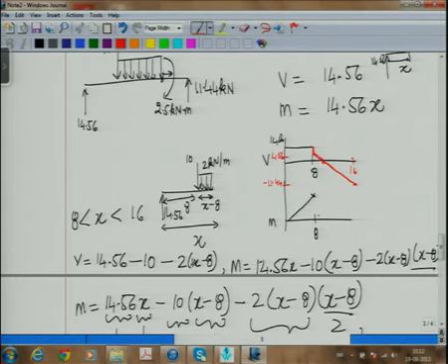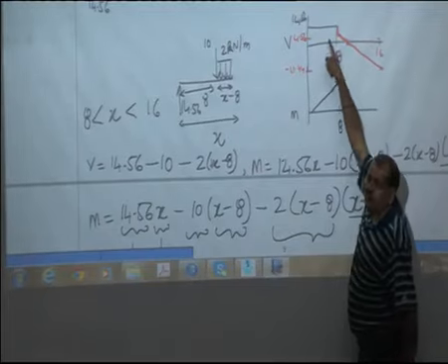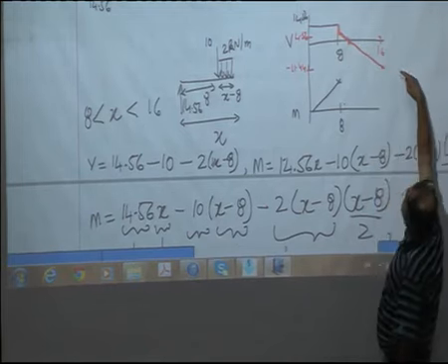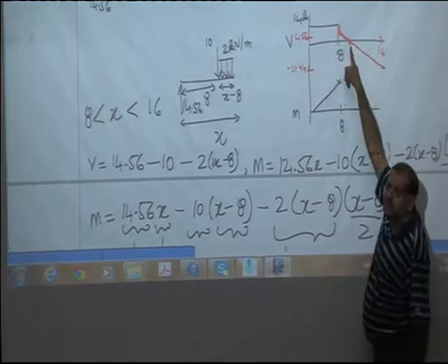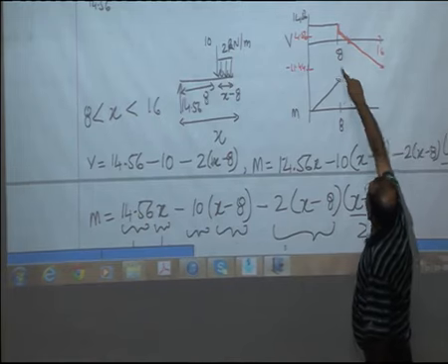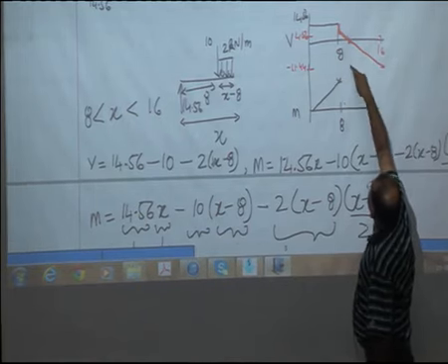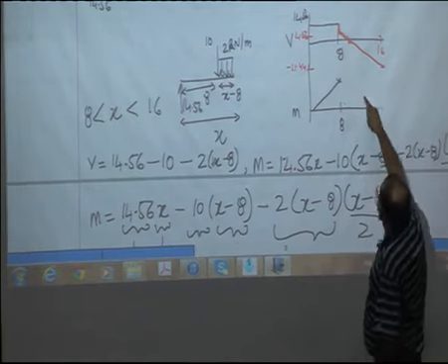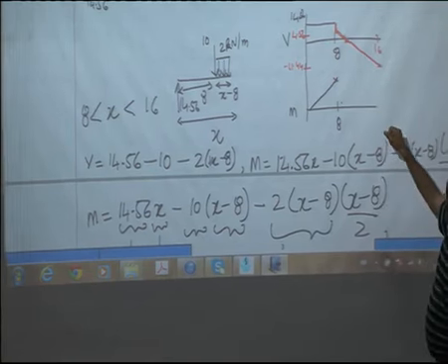Now for its nature, what you will know is that at this point the bending moment should become maximum. It will increase till this point because the area is increasing, and then we have a negative area after this point. So till this point you will have a quadratic curve which will increase, and after this it will start decreasing. Okay.